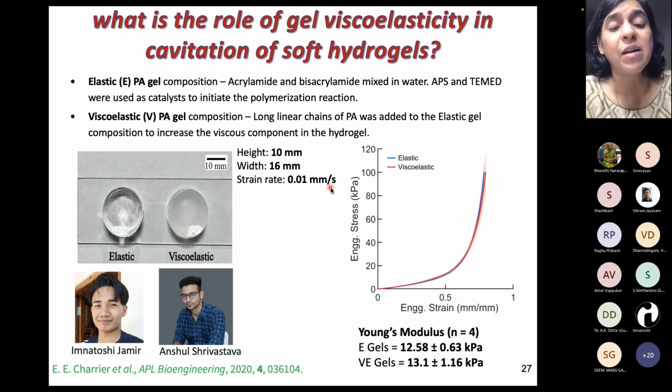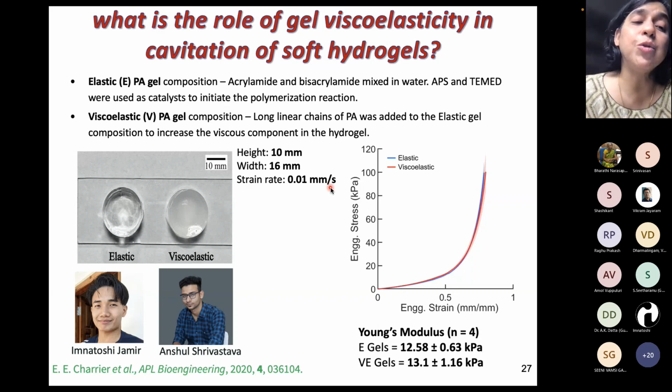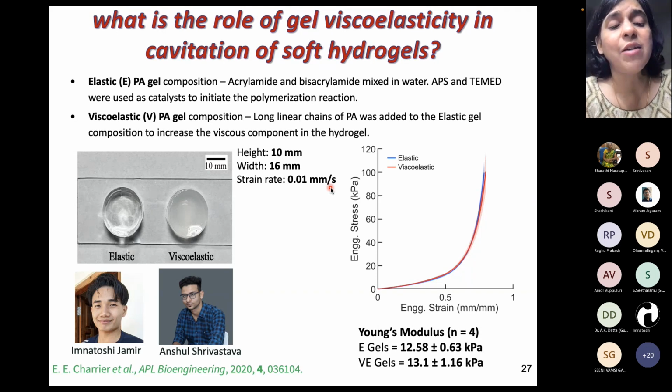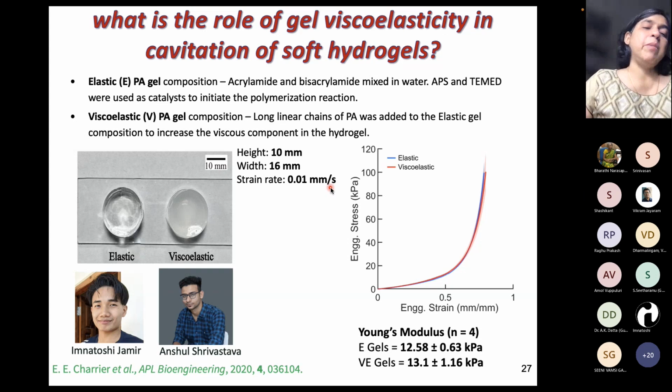The linear terms are controlled, but we can have differential contributions of viscosities. This is a very intriguing way of looking at gels and failures, and it allows us to control both the strain rates as well as the inflation rates inside this material, and look at the processes ahead of the crack tip.